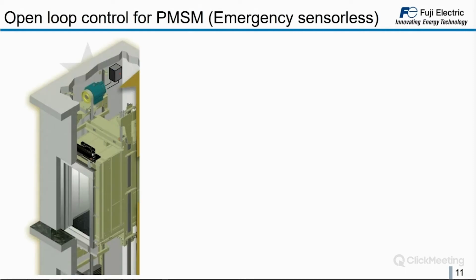So here in this graphic you have a very classical lift configuration nowadays. We have a lift shaft without machine room, with a synchronous motor, and with all the electronics either inside the shaft or on the door frame. From the architect's point of view, this kind of configuration is very nice. It's very optimized, but from the technician's point of view, it's a bit tricky because access to all the components is not easy every time, and especially in case of failures, everything is not so easy.